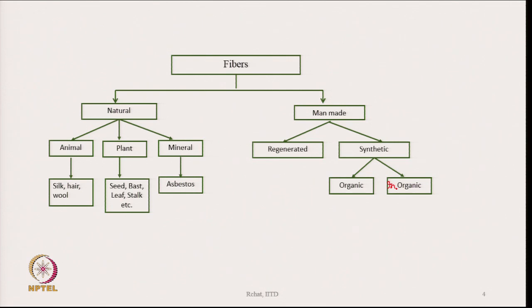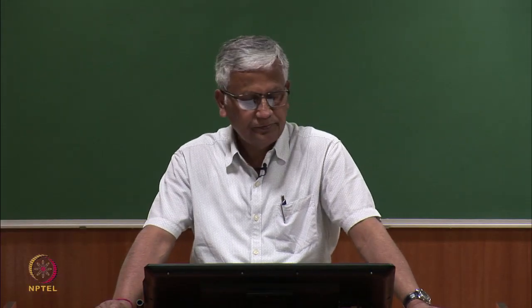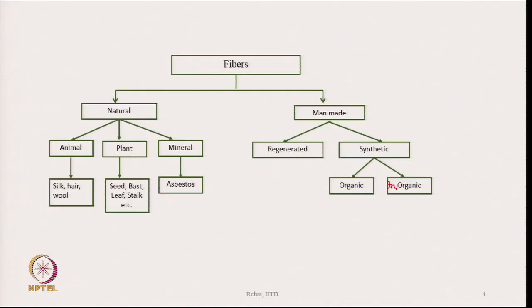So, you have so many raw materials available, and we have to decide which particular fiber we should choose for a given application. The only thing we should know about this is that natural fibers, their properties are more or less fixed. We do not have much control on their property. Whatever nature produces, we have to accept it, because we really cannot engineer the properties in natural fibers.